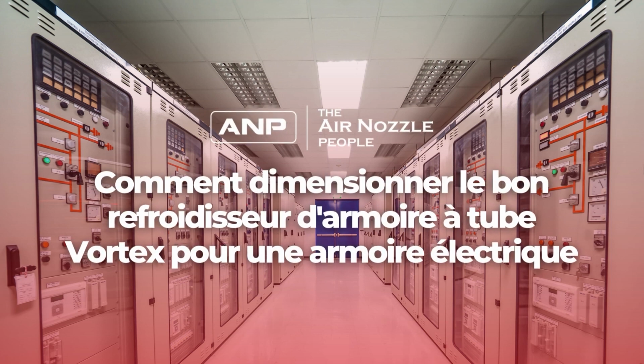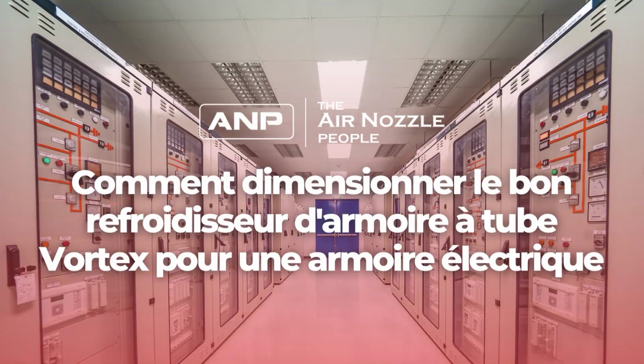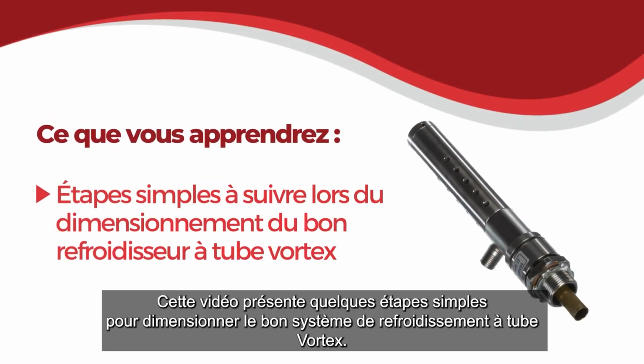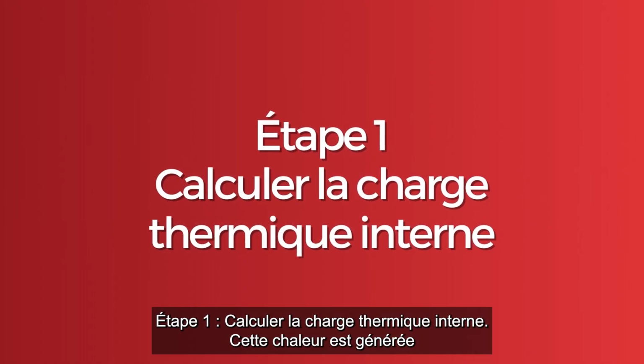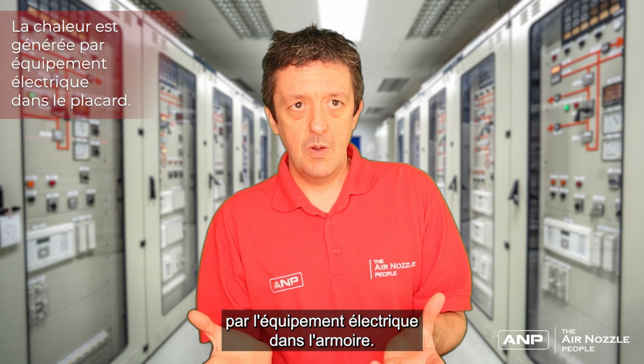How do I size the correct Vortex tube cabinet cooler for my electrical cabinet? This video highlights some simple steps into sizing the correct Vortex tube cooler. Step 1, you need to calculate the internal heat load. Now this heat is generated by the electrical equipment in the cabinet.